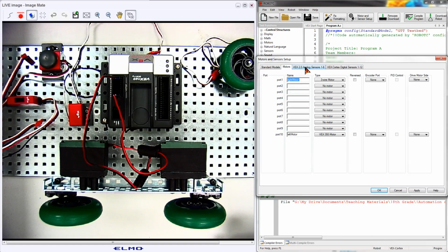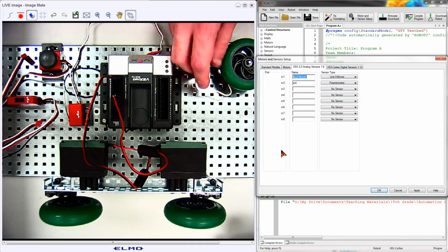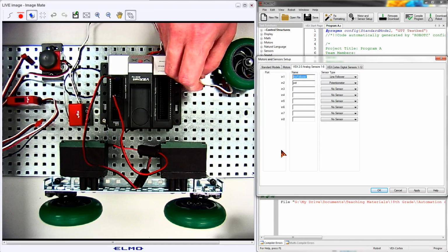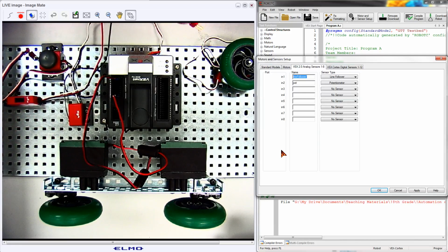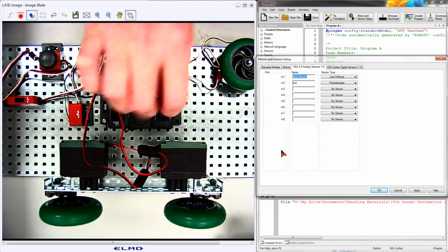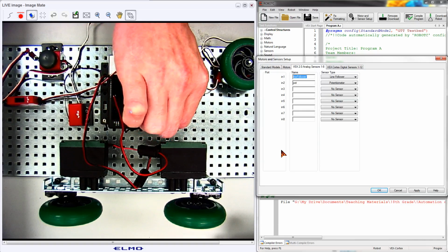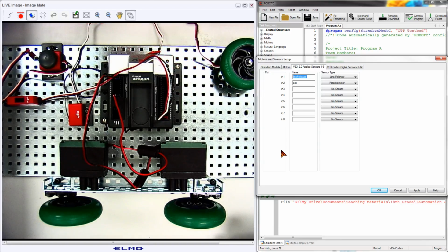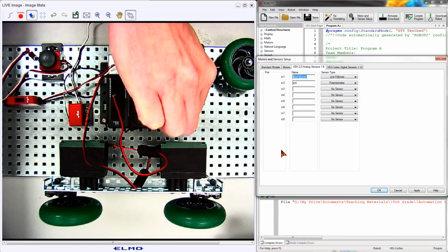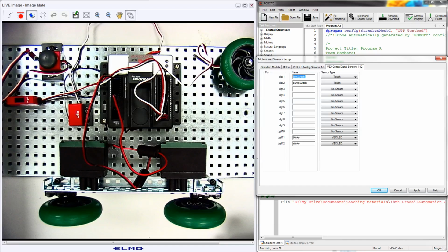So once we get the motor set, we have the analog sensors. We have a line follower and our potentiometer. Our potentiometer is going to go into analog 2, and our line follower, let's do the line follower first, into analog 1. We're going to make sure we put those in, and our potentiometer will go in right next to it.